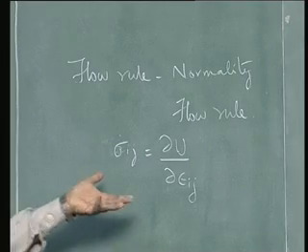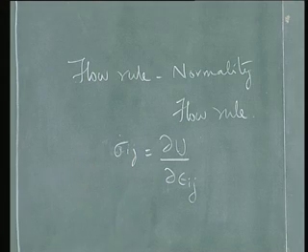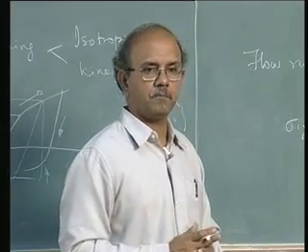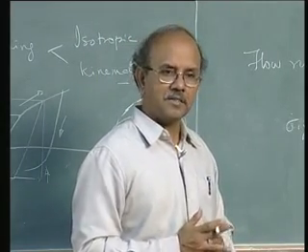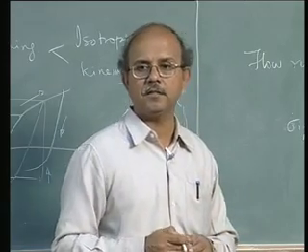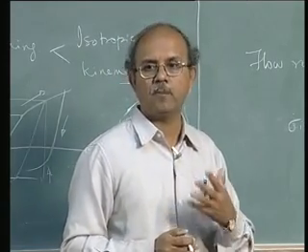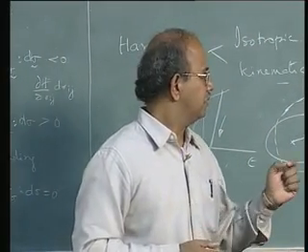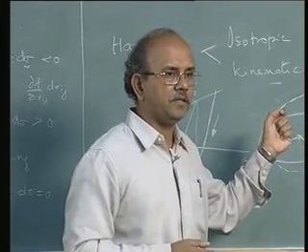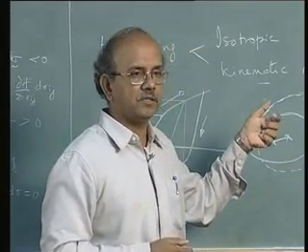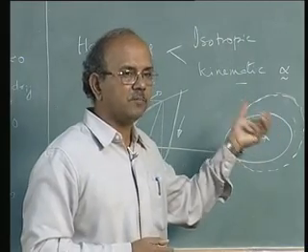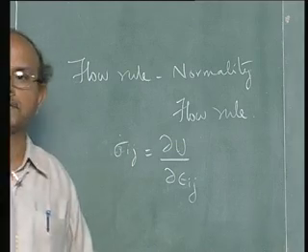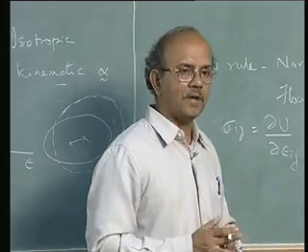So this was an inspiration for further work in plasticity, though the mathematical rigor of plasticity is still questioned by many of the purists. So in other words, there are still some loopholes in the mathematical theory of plasticity, but it is now good enough for us to apply to many practical problems. For example, if we use epsilon p for hardening, there are purists who question how far you are catching all the effects that are happening inside by epsilon p. But it does not matter, for all practical purposes the current theory of plasticity explains and is valid.